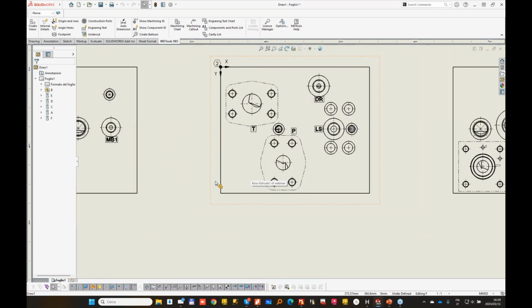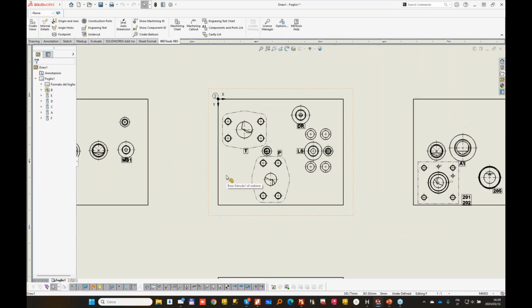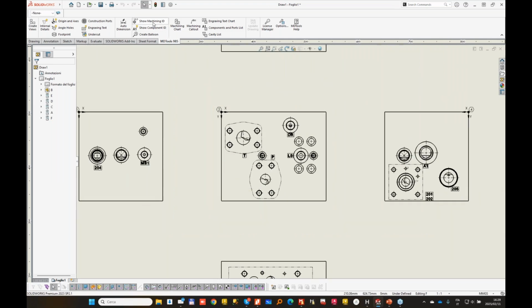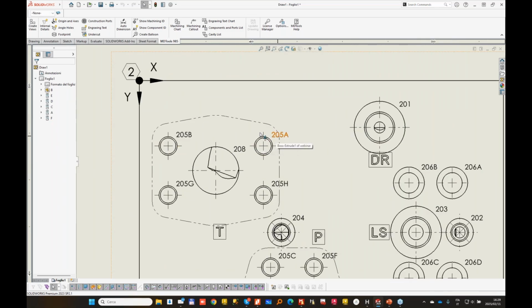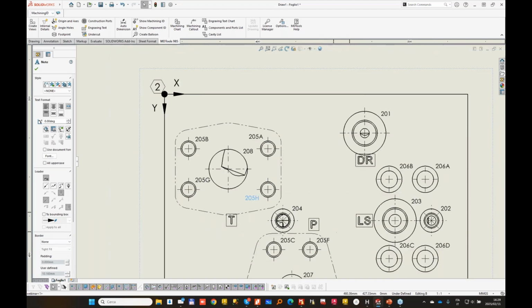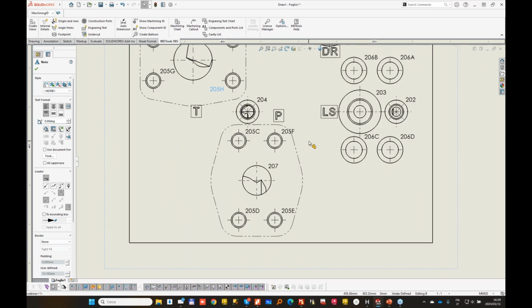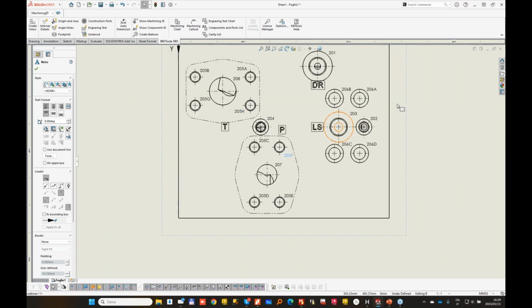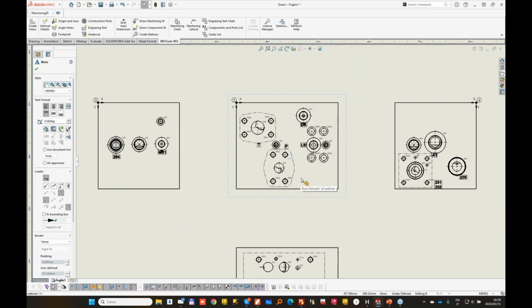So for those doing a drill chart, we need the machining IDs. There are 2 possibilities for showing machining ID. One is the following, which is the one I most commonly use. Basically, MDTools is attaching to each cavity the number that we have generated in the part file. To this number, there will be a corresponding line in the drill chart.